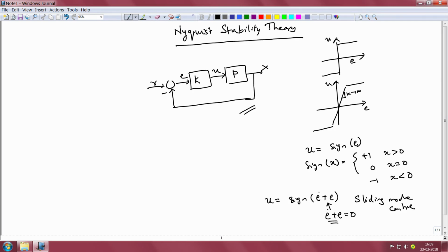Now the two techniques that I talked about here are nonlinear control techniques. There are several others, some of them linear, some of them nonlinear, but it is satisfying to underscore the fact that as far as getting x of t equal to r of t is concerned, all of them attempt to achieve high gain for the controller.